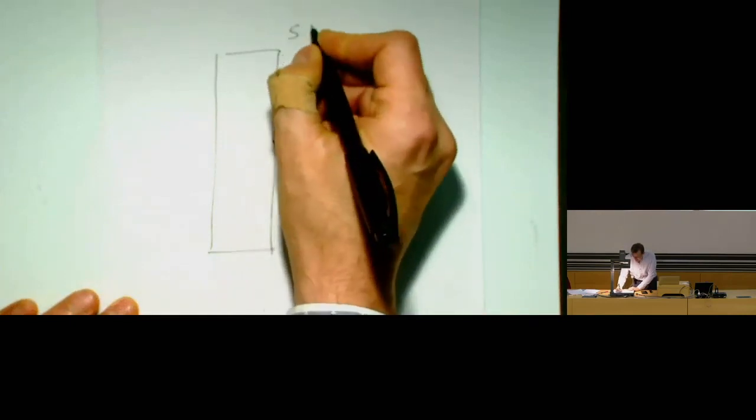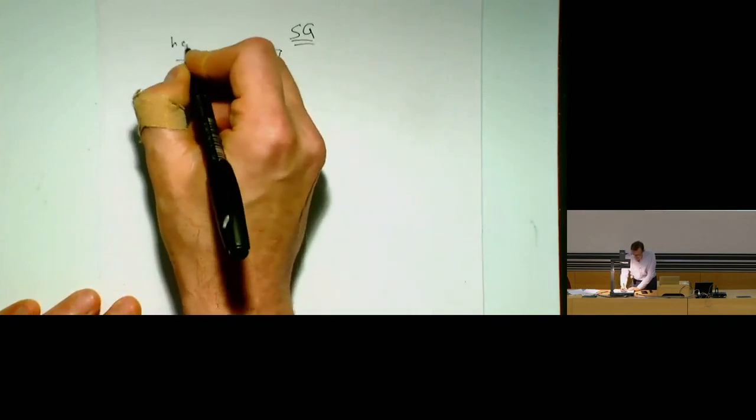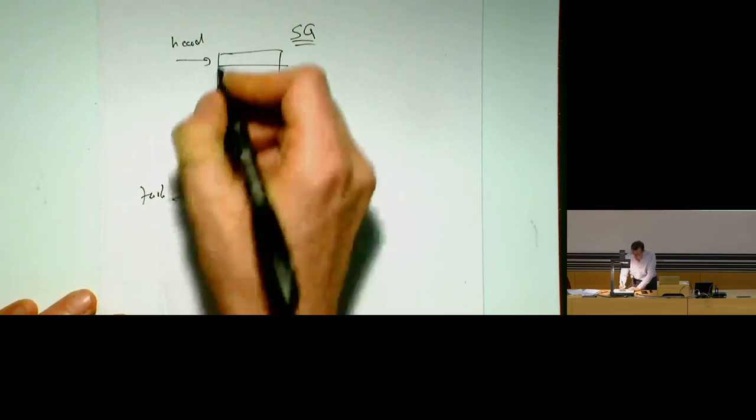I'm going to make it simple. This is a store queue. This is an in-order list of all of the stores that are in the machine. You have a head. This is all hardware, of course. You have a tail. And what do you have over here?